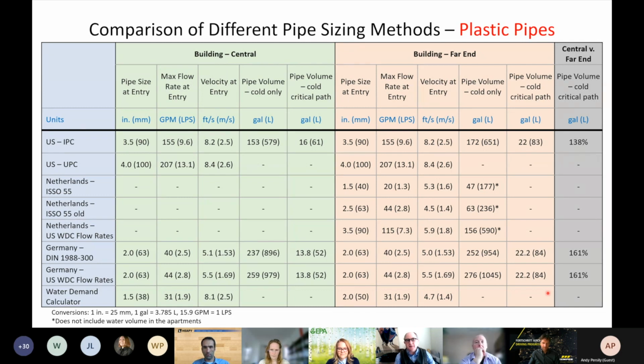I like that idea a lot, of separating the cold and the hot plumbing pathways. I think it makes a lot of sense from an energy perspective as well as the health and safety perspective. Hots with hot, colds with cold, never the twain shall meet until you get to a fixture. Yeah, basically you don't want to chill your ceiling void down by cold water.